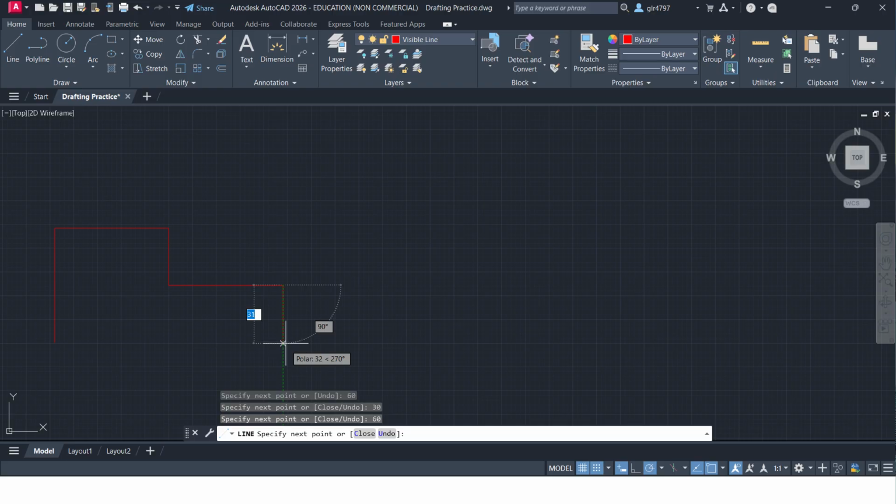You see these little green dotted lines? They're called guide rays. I can use them to my advantage. When I move vertically, I have a guide ray that goes up and down, the green dotted line. If I hover over the little green box at the bottom left point, and it's saying endpoint, that's good. So hover over it, don't click it.